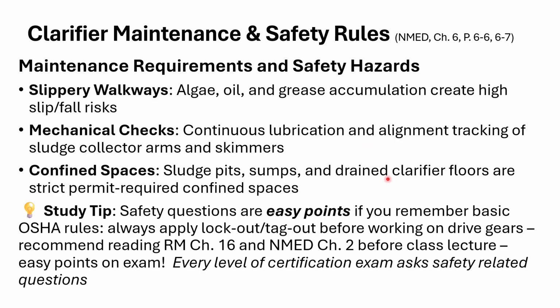Okay. Confined spaces. So the sludge pits, the sumps, and the drained clarifier floors, those are what are called permit controlled confined spaces, or permit required confined spaces. Okay. You're not going to go in there unless you have a permit to do so. And you're going to have some safeguards, and we'll talk about this in the safety chapter. But those are permit required spaces to get into confined spaces. So again, these are easy points.